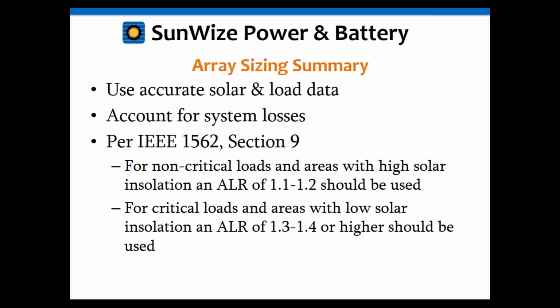Okay, as I've mentioned several times, we're going to be referring back to the IEEE 1562 for this. And again, your design is only going to be as accurate as the solar data and the load data that you're using. And of course, be conservative with your system losses. And I mentioned before the difference between some non-critical and some critical loads.